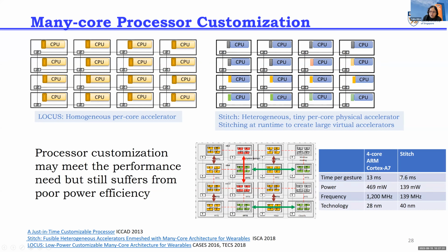And then instead of having these instructions stored over here, you have actually mapped this entire data flow onto the hardware, and you have configured the hardware so that it can execute these things automatically, right? So basically what happens is that your data comes in, and then it reaches the first of these things in the data flow, and then it triggers the next one, and so on and so forth. This is how this whole processing works. So instead of the stored instruction concept, you have the entire data flow being mapped onto the hardware.